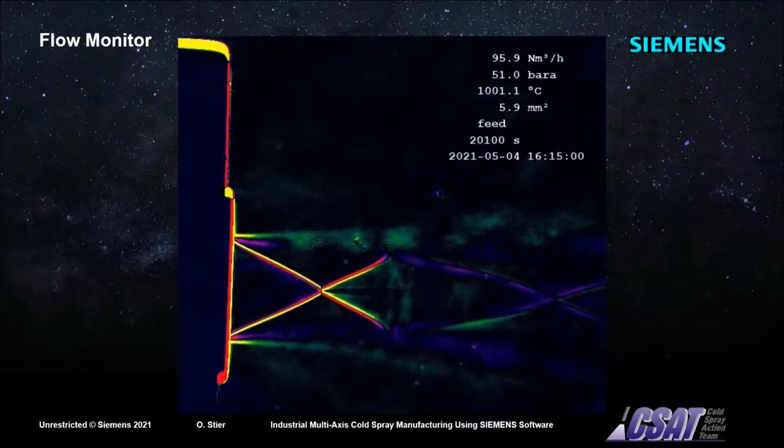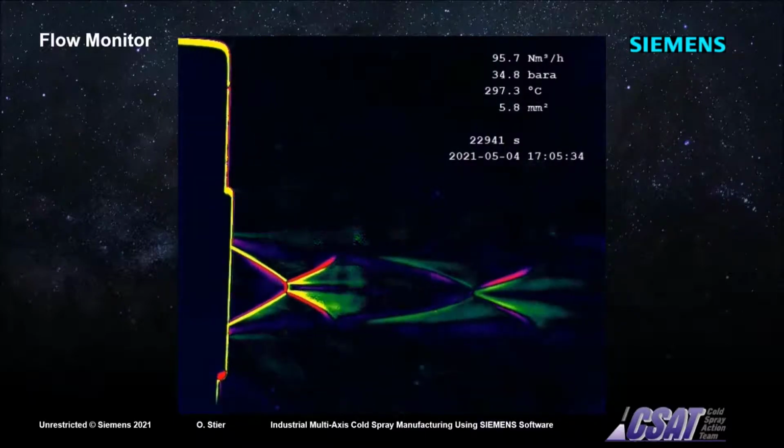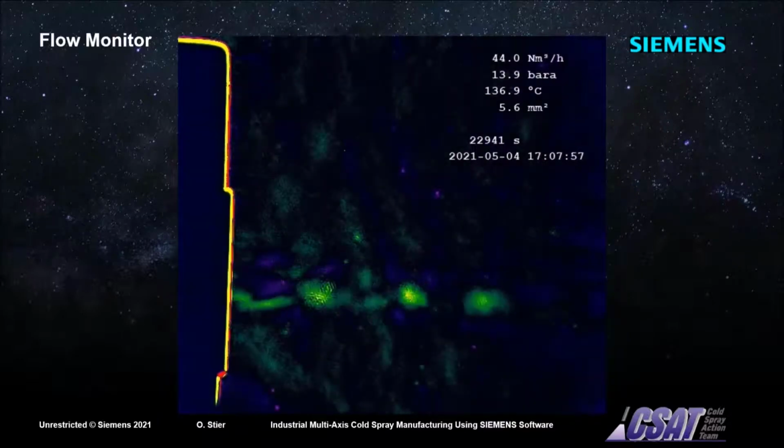Some of those material pile-ups may erode subsequently, but eventually one of them will block a significant portion of the cross-section area. None of the proceedings can be sensed by the cold spray system control until the choking cross-section diminishes due to massive blocking. The changes take place in the supersonic section of the flow, from where no information can propagate backwards to the stagnation chamber where the temperature and pressure sensors are located.